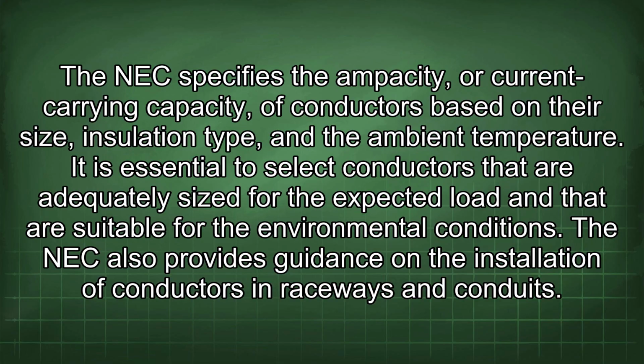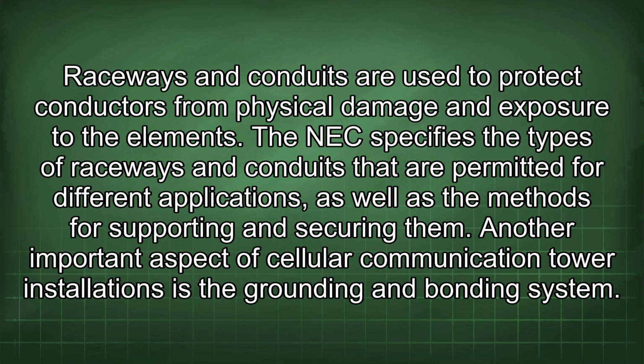The NEC also provides guidance on the installation of conductors in raceways and conduits. Raceways and conduits are used to protect conductors from physical damage and exposure to the elements. The NEC specifies the types of raceways and conduits that are permitted for different applications, as well as the methods for supporting and securing them.